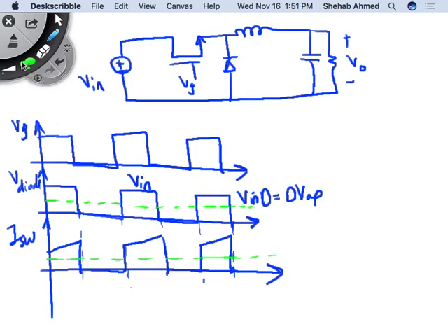It's this peak value of inductor current, which we call IC for now. And then this average value is D times IC. We agree? IC here is this peak value of this current. Okay, so if that's the case, let me propose to do this. This is my V input.